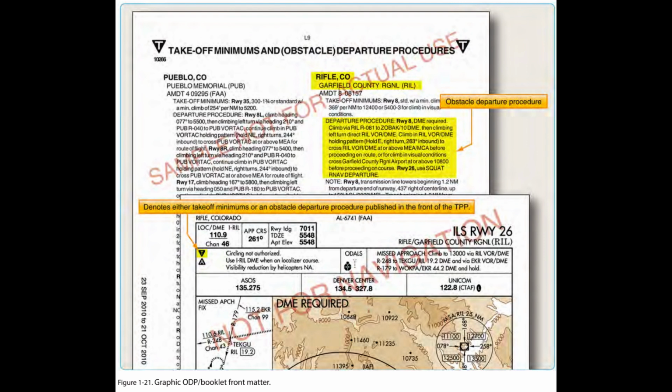This is considered the default IFR departure procedure for a given runway and is intended for pilot awareness and use in the absence of ATC radar vectors or SID assignment. Text is not published to allow an option to use a SID or alternate maneuver assigned by ATC, e.g., climb heading 330 to 1200 before turning, or use Manchester departure, or turn right, climb direct ABC very high frequency, VHF, omnidirectional range, VOR, or as assigned by ATC.